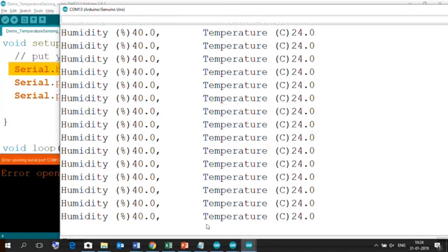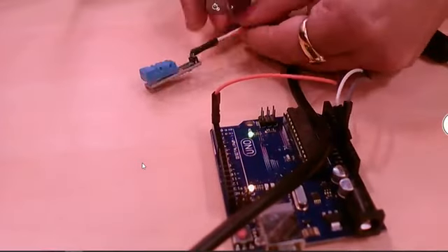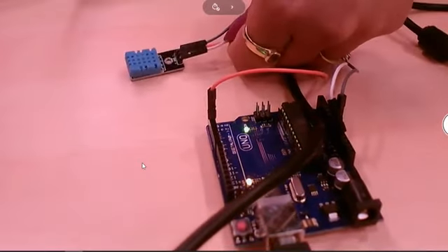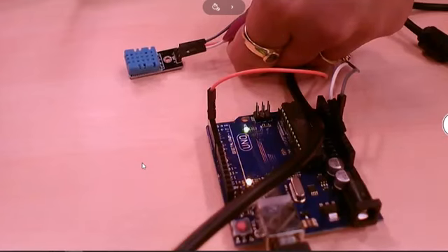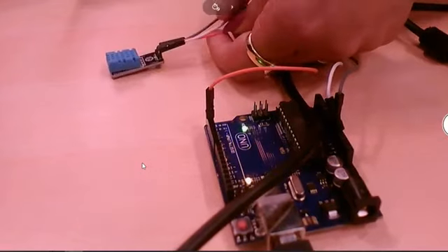Now, what I will do, I will show you at the output level. Just remember here, currently 40 and 24 is getting displayed. After a delay continuously in the loop, again and again the microcontroller is sensing the temperature, printing it. After some delay, again sensing, it is printing. So, showing it on the circuitry level, this is how your temperature sensor looks like, DHT11. It has the pins plus, negative and data signal. So, in all 3 wires are coming.